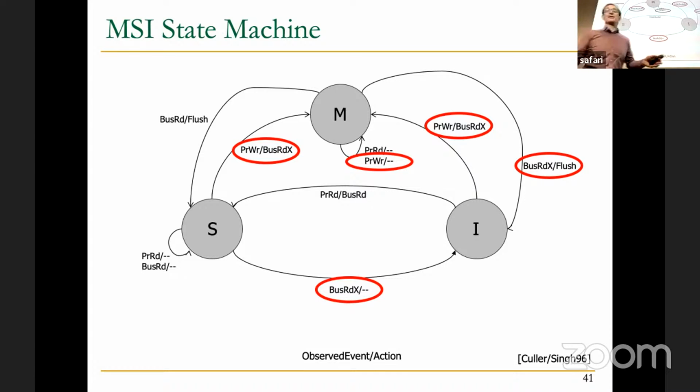Yeah. I mean, there is basically a bus arbitration that happens. Only one of them will win the bus. And the first one that gets the bus will invalidate everyone, basically. But this becomes more difficult when you start pipelining the bus, etc. But yes, you need to have some ordering. But in the end, you have the ordering in the bus. A single bus helps that ordering. So there are some race conditions that you need to deal with, even when you have a bus, actually.